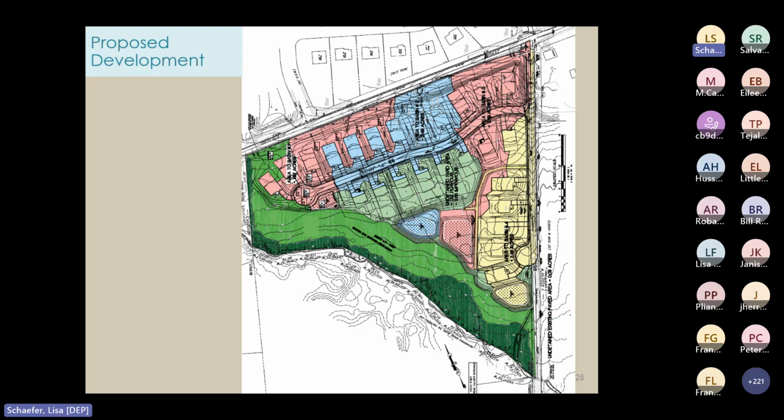Its contributory drainage area is also, as you can see, over here in blue, and it's way too far away from the basin. Now, basin 3 is the area towards the right that's also in pink. The basin is too far from the motor vehicle surfaces like the entrance road over here, as well as the internal roadway. The yellow area is for basin 4. And look how far runoff has to travel down the side road before it's collected in inlets and then piped to the basin.